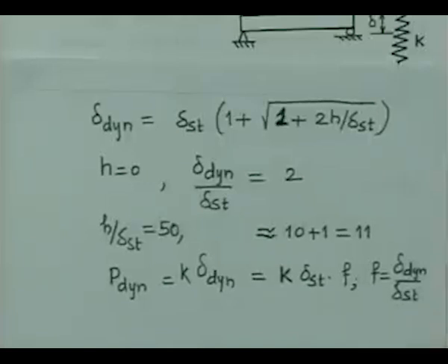So this dynamic loading is very severe, and therefore while considering the design of components under dynamic loading, one might take into account the action of the dynamic loading by invoking a factor of the type given by F here, which is nothing but the ratio of the dynamic deflection to the static deflection.